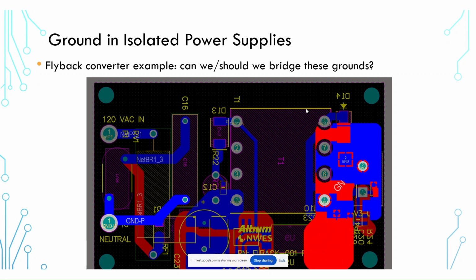Well, it can be measured. You can actually measure it, I believe, with an LCR meter. You could also just measure it using a leakage measurement. So basically you apply some signal on one side, you measure the signal on the other side, and then you determine what the capacitance is.